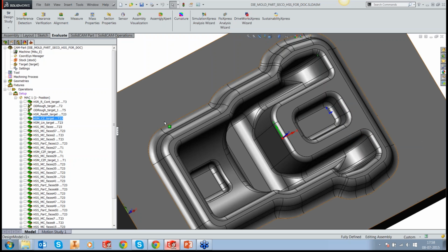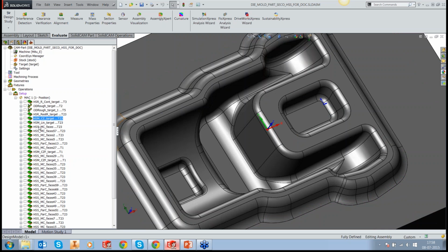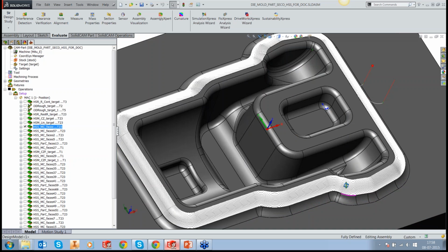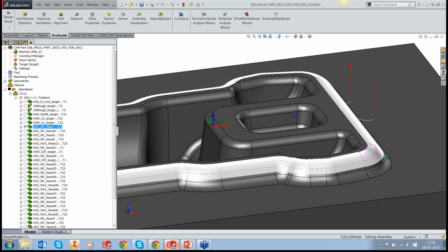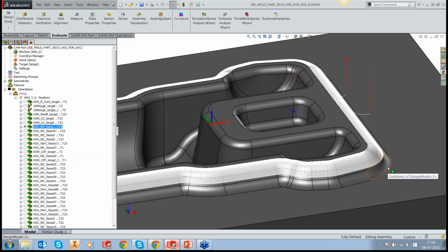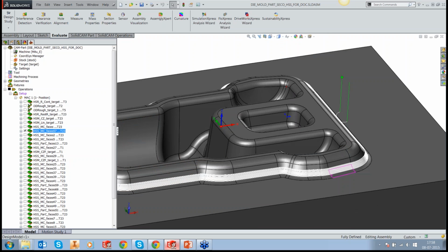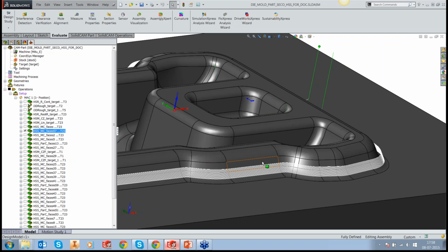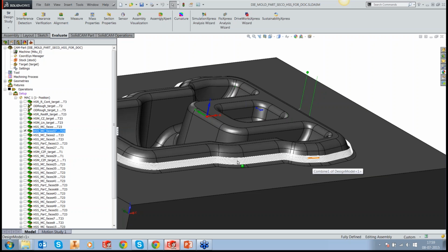For example, you can start looking at the toolpaths that we generated for this. The first one was for the outer fillet. The outer fillet was completely finished using HSS and spiral cutting. That means once it engages, there are no more side steps involved in cutting the part. The next toolpath was also the flat area here. You can see that each of these patches are machined separately. We are not continuously machining this. We are handling them separately.